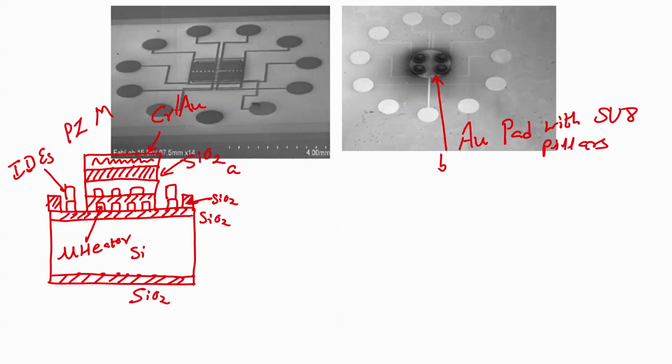The reason is that these metals have poor adhesion to the substrate, and to improve the adhesion we have to use a combination of another metal. In case of gold, gold has poor adhesion to oxidized silicon, and that is why we have to use a thin layer of chrome along with gold. That is why we always write chrome gold, but the thickness of chrome is extremely thin compared to thickness of gold, alright. So, what is the next step after this chrome gold?